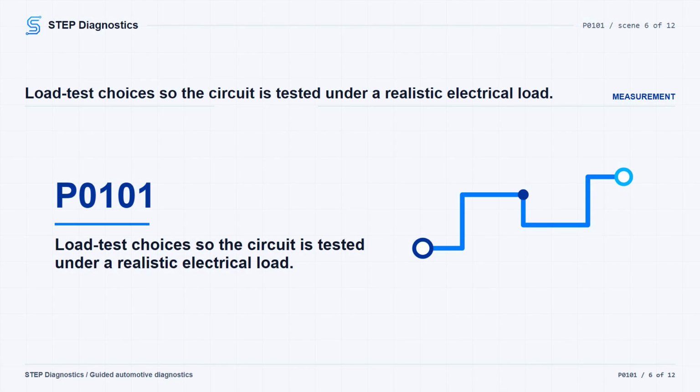For a power-providing circuit carrying approximately 200-1000 mA, load the circuit with a 250-350 mA test light, and measure voltage with the DMM while the light is connected. If voltage drops under that load, excessive resistance is indicated. Conductor size helps you choose the right kind of load.